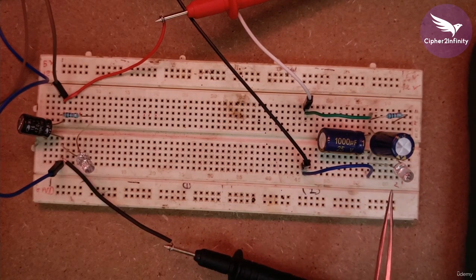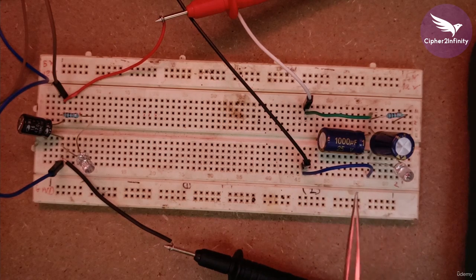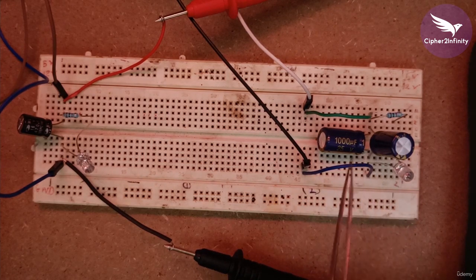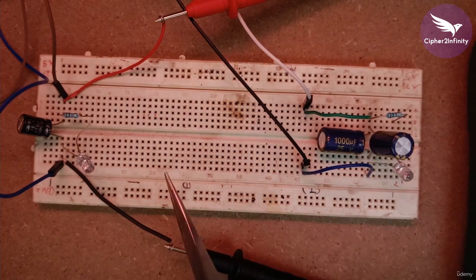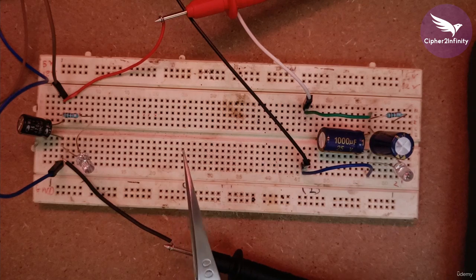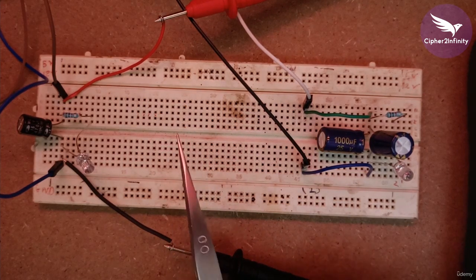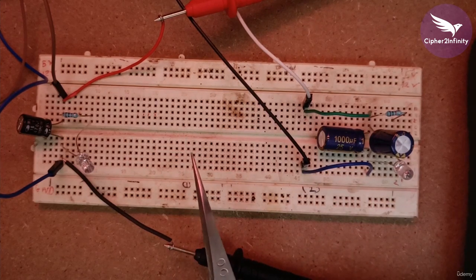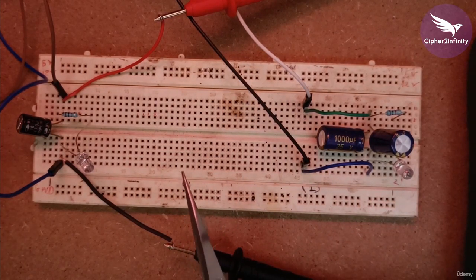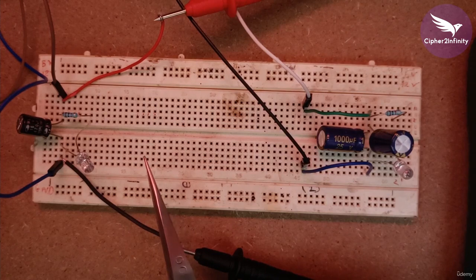So we saw that this particular LED took even more time to switch off. So this LED took the same time, but this time this particular LED took even more time. It's because of these two capacitors that we have connected in parallel. So that's what I wanted to tell about the energy storage point, and I hope that it's clear now. Based on the capacitance, it will be decided how much energy that particular capacitor is going to store. In the end I will just show you this demonstration one more time.